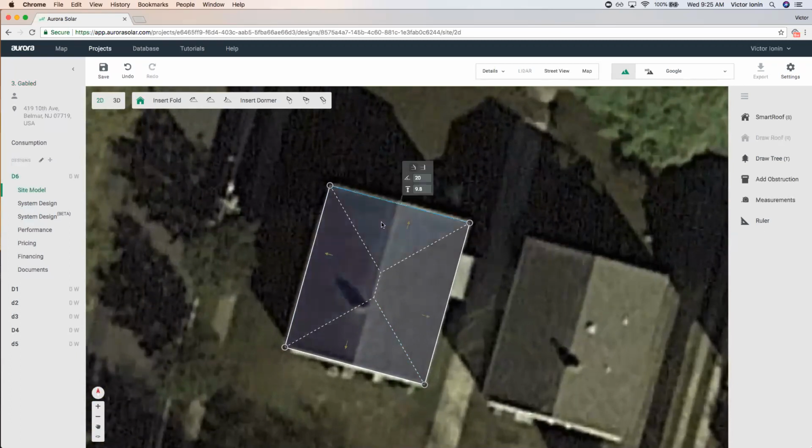You're now going to click on roof faces that do not exist or aren't supposed to be there, like this north triangle. I'll click on it, and in this little modal that pops up, I'm going to select unpitch. When you unpitch a roof, you're taking that 20-degree sloped roof and turning it into a 90-degree wall. From the top-down view, what it looks like is the roof disappears. So let's do that for the south face, unpitch.